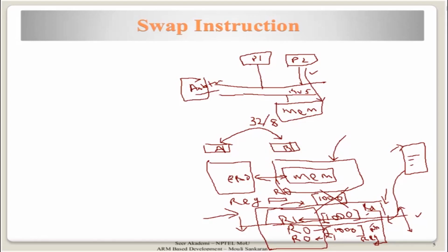I will explain why it is important not to have any other processor or any interruption modify the value before this swapping happens. So to make sure that this swapping operation is done without any interruption between the memory cycles, we are using a swap instruction. So how does it make sure? Because the swap instruction is executed in one particular processor. You are executing the swap instruction in this processor.